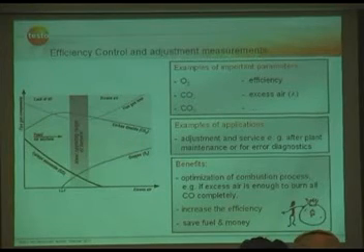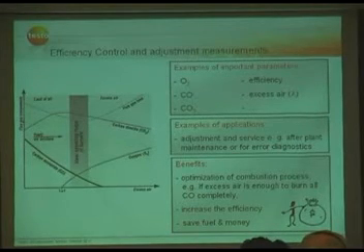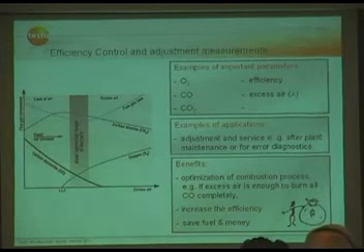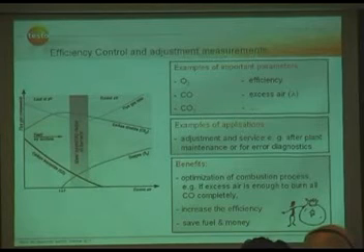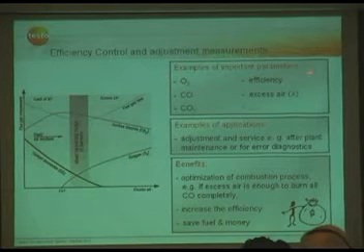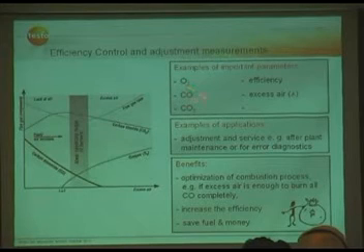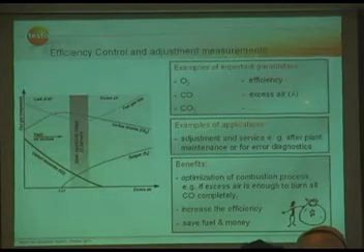And if you have your own fuel, which is not a standard fuel, with our software Easy Emission, you can just enter the fuel-specific data, and the software will calculate all necessary parameters or factors, which can be transferred to the instrument, and based on this new fuel, you can do all your calculations very easily. Examples of important parameters for control and adjustment are oxygen, CO, CO2. Based on these, the instrument will calculate efficiency, excess air, and other important parameters.